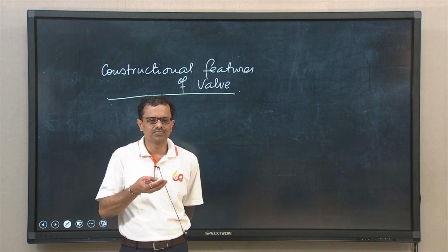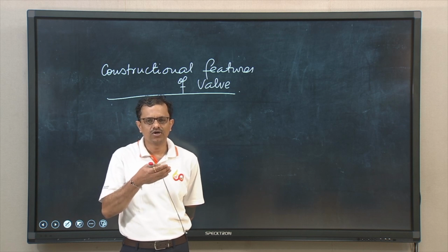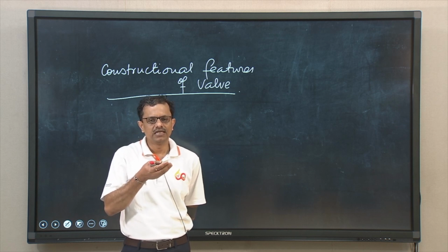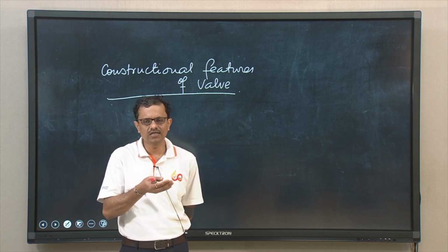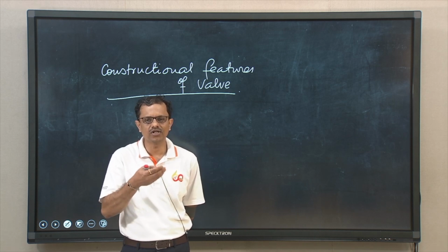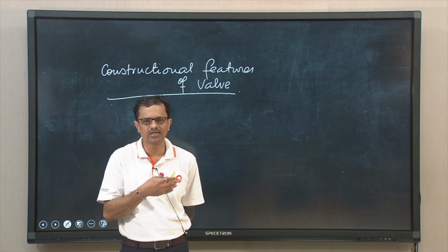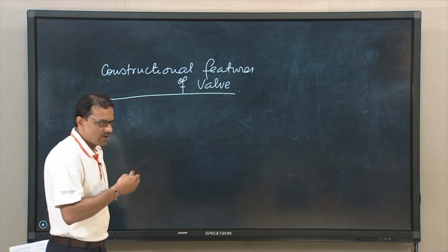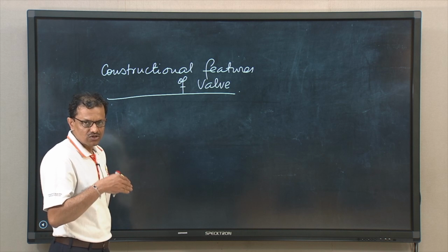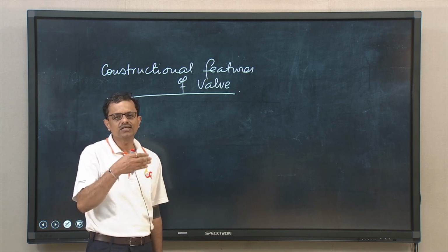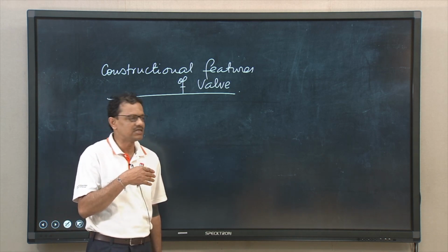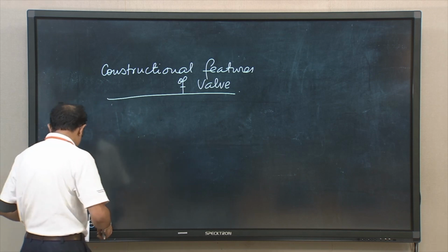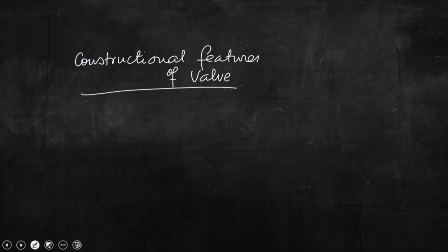Timely flow or timely intake of fresh air or charge and also timely expelling out all the combustion gases from the cylinder is very important for an efficient operation of engine. So, valves play an important role to control the flow of incoming air as well as leaving of combustion gases from engine cylinder. So, if we draw the constructional feature of the valves in several arrangements, one is known as valves in block. So, case A,